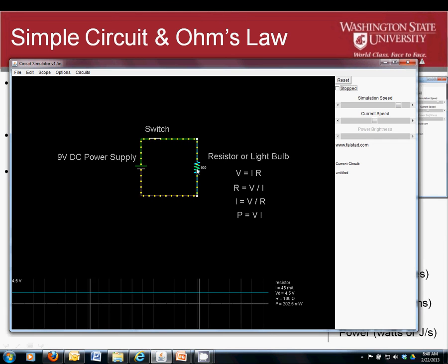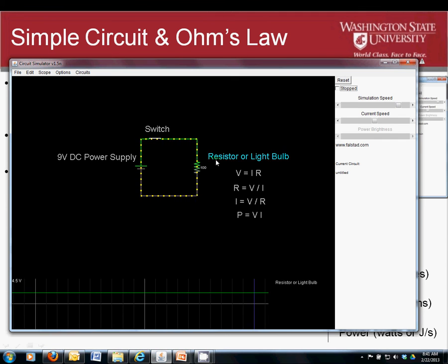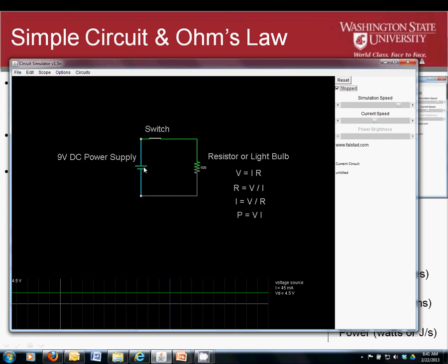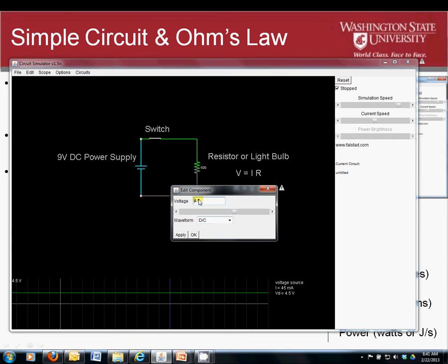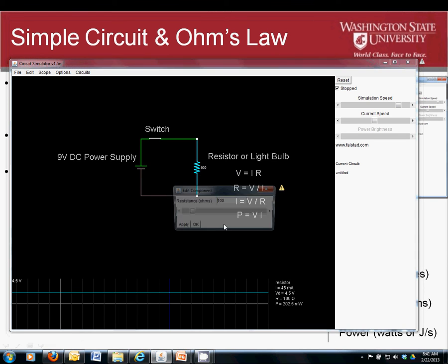Now the power has dropped by a factor of 4. Because the power is a product of voltage and current, there happens to be a square function in there that's not obvious, but the power formula can be shown as I squared, the current squared, times the resistance. And so that's why it drops by a factor of 4. Let's change the resistance value to half what it is. Let's stop this model, edit, switch the resistance value, oops, wrong spot, switch the resistance value to 50 ohms.